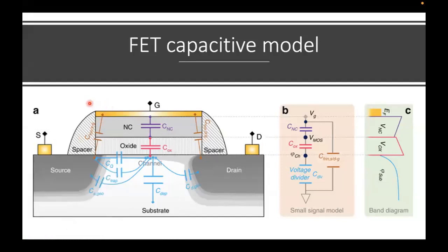Okay, so let's focus on the different capacitances that may exist in a MOSFET structure. Generally, in order to detect the capacitance in a structure, you have first to justify why we should have a capacitance. So, generally speaking, the first and the main source of a capacitance is having a non-conducting layer between two conducting layers.